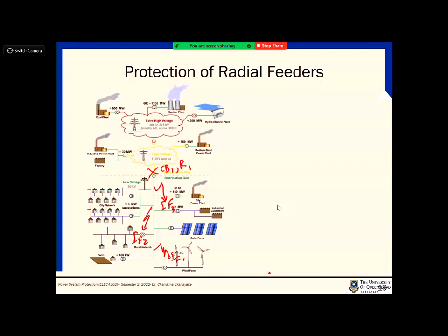What are the advantages and disadvantages of that sort of protection scheme? Say at that circuit breaker, you can say, okay, I can set a fixed time, right? I don't even have to go for IDMT. I will say an instantaneous relay, right? I will put an instantaneous relay at circuit breaker R1, so that for any fault, my feeder will be disconnected. Great, right? Very fast operation. Now, what are the problems associated with that? What are the challenges there then? What do you think?